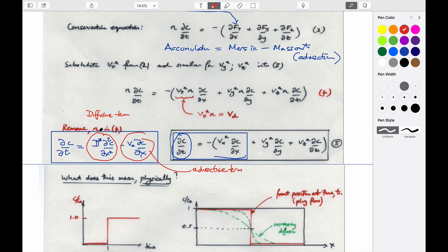And I suppose we should also make the case that if you wind back your minds to what we talked about maybe in the first 15 minutes today, this Fickian diffusion spreading of water in a beaker looks exactly the same as if it flows through a porous medium and gets agitated, mechanically distributed by its flow through these pores. So this is the diffusive term, but it's also, as we'll find out, a dispersive term as well. Dispersion being this kind of mechanical mixing.